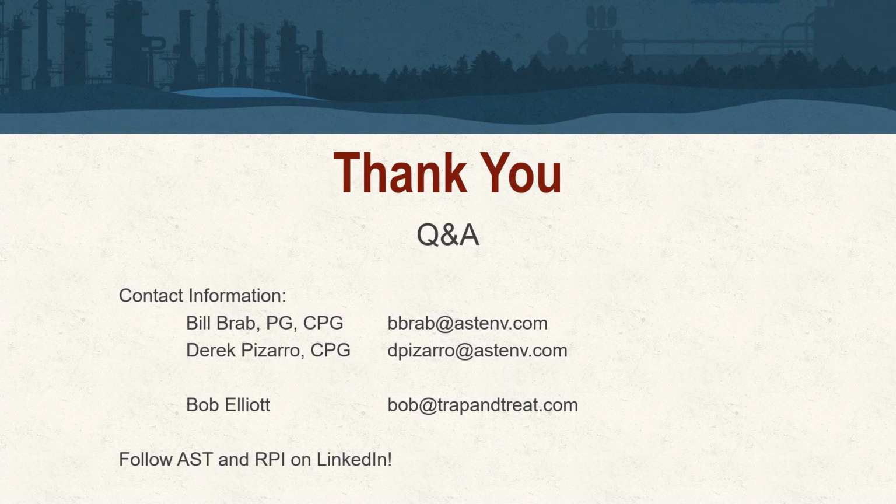Great. Similar question. How do we typically assess radius of influence in a fractured bedrock setting? And does that estimate change based on bedrock, fracture network, or other variables? And how do you estimate that at the outset? Yeah, it's a good question. The majority of our distribution verification is by the use of transducers and monitoring the surrounding network as we're working.